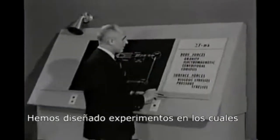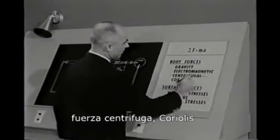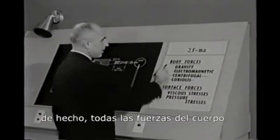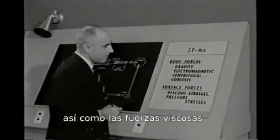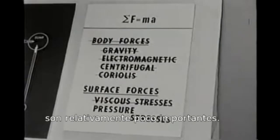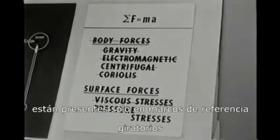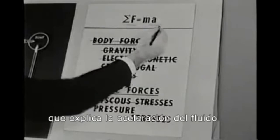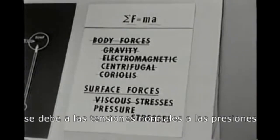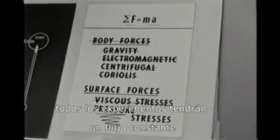we have designed experiments in which gravity, electromagnetic, centrifugal, Coriolis, in fact all body forces, as well as viscous forces, are relatively unimportant. The centrifugal and Coriolis forces referred to here are present only in rotating reference frames. The main force, accounting for the fluid acceleration, will be due to normal stresses, to pressures. All the experiments will be in steady flow.